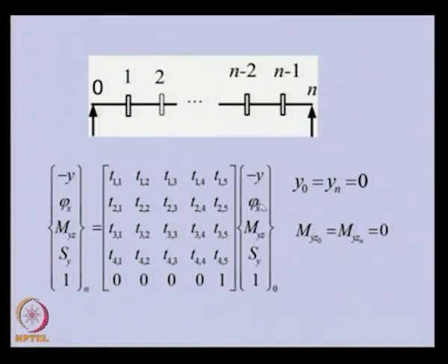If there is unbalance in the system, the form of the overall transfer matrix will be this. So, the last row will be 0, 0, 1. These correspond to the unbalanced force. The other terms are multiplications of various point matrices and field matrices, and basically all of these will be functions of omega, which is the spin speed of the shaft for forced vibration. For free vibration these terms will be 0 and we can take omega as the natural frequency of the system.